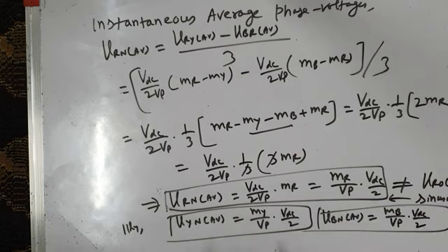This is very important. It makes it clear that although with the injection of the common mode signal MCM in all three original modulating waves, the modulating waves got modified to MR star, MY star, MB star, they no longer remain sinusoidal, and our pole voltages also are scaled versions of the modified modulating waves. Instantaneous average pole voltages are also not sinusoidal, but that does not affect inverter output voltages as line voltages and phase voltages.